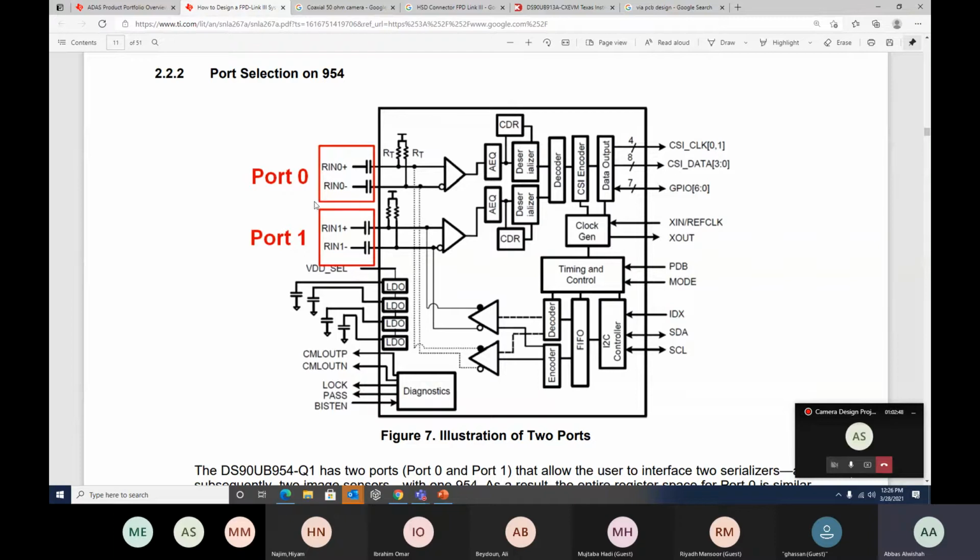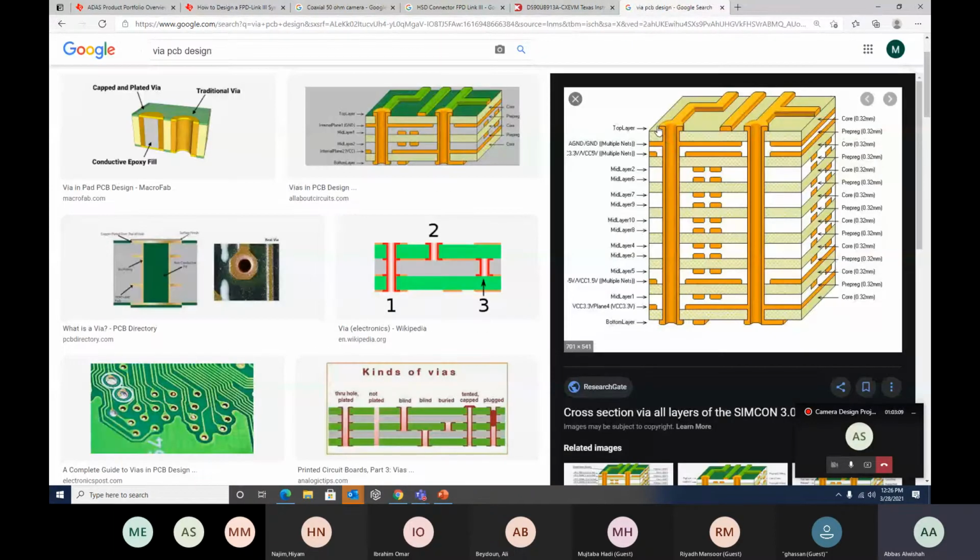Or is it software? Or if we have too high of an input, then we need to look back further this way on our design. But if it's coming into the port, and then we got an issue on the output, then we need to definitely check between them. And the only way to check between them is, as a hardware design engineer, you need to consider these vias. Put them in first.